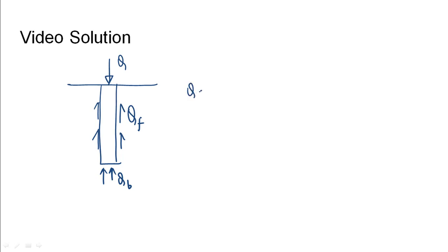So let us visualize the pile. So if this is our pile, there are two kinds of loads that act on a normal pile. So if the load Q is getting acted, this load is shared by the frictional load and the load at the end bearing. So Q is given as QF plus QB. This is in the case of a normal pile.